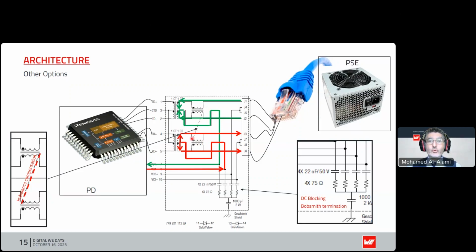So as an alternative to that trifilar, what we have got is a bifilar, but to stop saturation from taking place, we wrapped those wires here and those wires there around the same core material, in which case both currents going in and currents coming out will give you a net flux in that core, which is one core, of 0. So there is no saturation as a result of power currents flowing through.